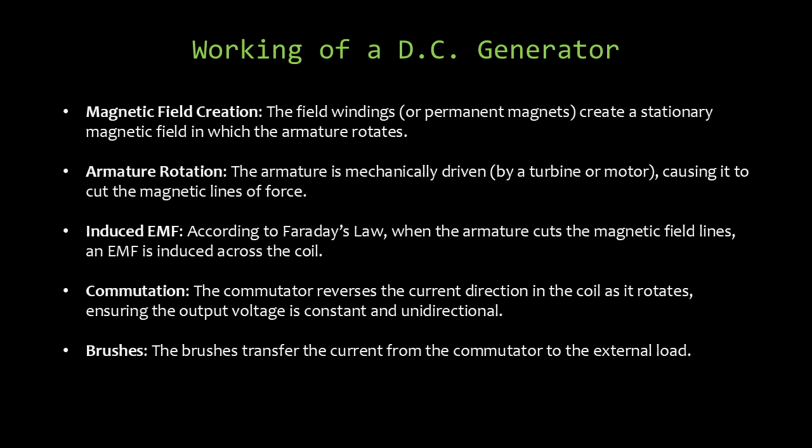According to Faraday's law, this motion induces an electromotive force across the coil. The commutator plays a crucial role, reversing current direction to ensure constant, unidirectional output. Brushes then transfer this current to the external load, completing the electricity generation process.